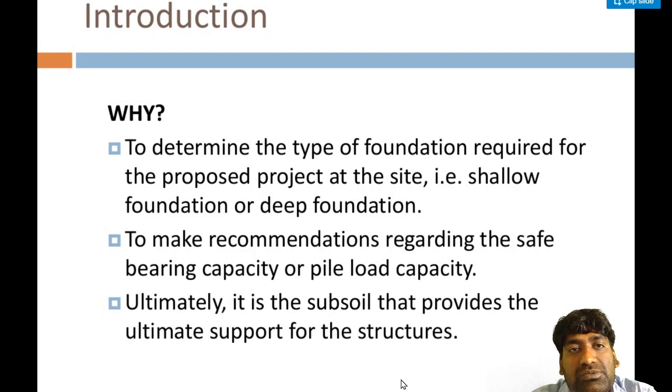Why do we carry out subsoil exploration? To determine the type of foundation required for the proposed project at the site, that is, a shallow foundation or a deep foundation. To make recommendations regarding the safe bearing capacity and pile load capacity. Ultimately, it is the subsoil that provides the ultimate support for the structures.